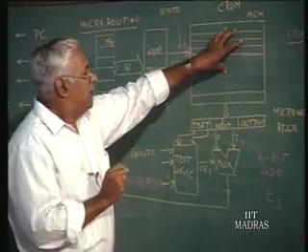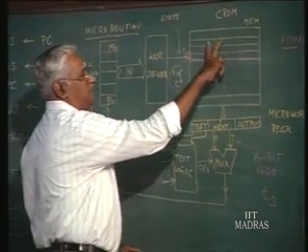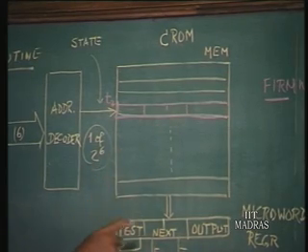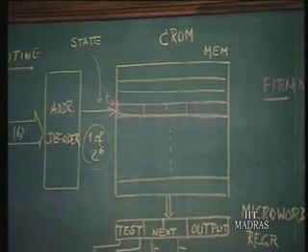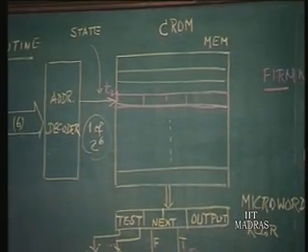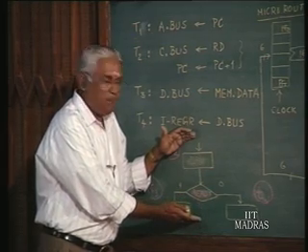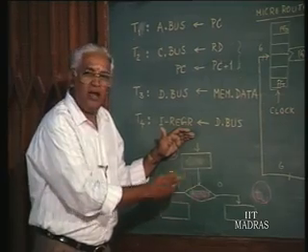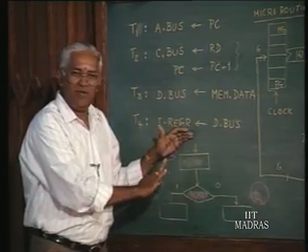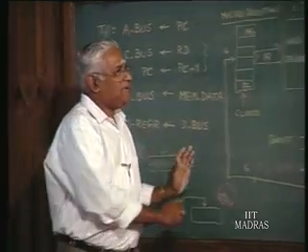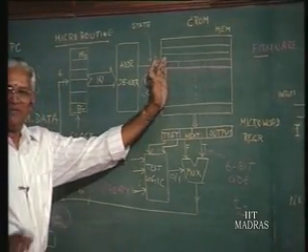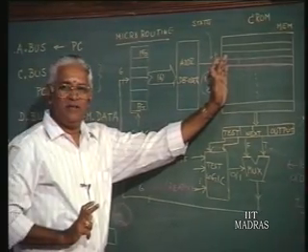And as I already explained, this implementation has flexibility mainly because it is not completely wired. What we mean is, the ASM chart really gives you the behavior of the whole machine, and in terms of codes, this read-only memory is going to have them, correct?